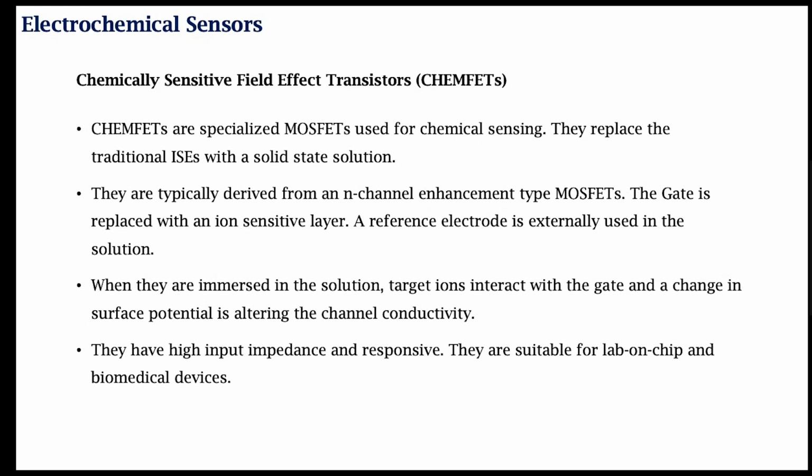So when we do that, the target ions will interact with the gate, and the change in the surface potential changes the channel conductivity. Note that they have high input impedance and are highly responsive. And because these are also FETs, we can miniaturize this at a high level, and they are suitable for lab on chip and for biomedical devices.